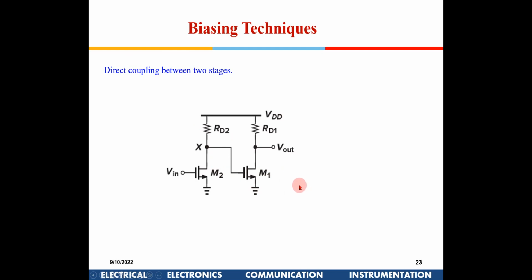Usually in our internal architecture we will see only this kind of thing. We don't add extra legs because it is unnecessary. If you see IC 741 circuits and all, there will be a lot of this, because of the DC voltage at a particular stage. Suppose the requirement is such that the DC operating point here is 1.8, here it is somewhere in the middle, 0.9, whereas the requirement out here is only, say, 0.7 volt. There will be a mismatch between these two DC voltages, right?